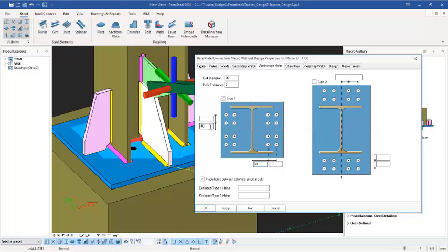So the same thing I will do on this other side. I will key in 60 right there. Alright, click on apply. You can see the hole has actually come up. So I'm having altogether a total number of 4 holes on this plate right there for the base plate. Alright, the bolts diameter is 20 and then the tolerance is 2. Alright, so everything is good now.